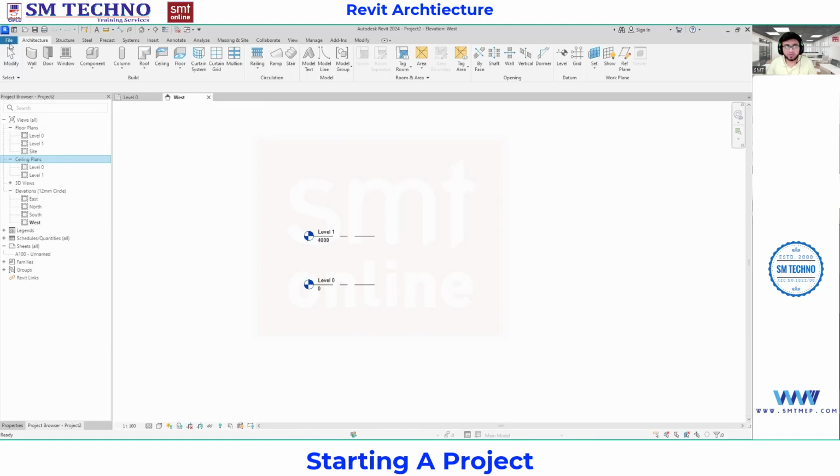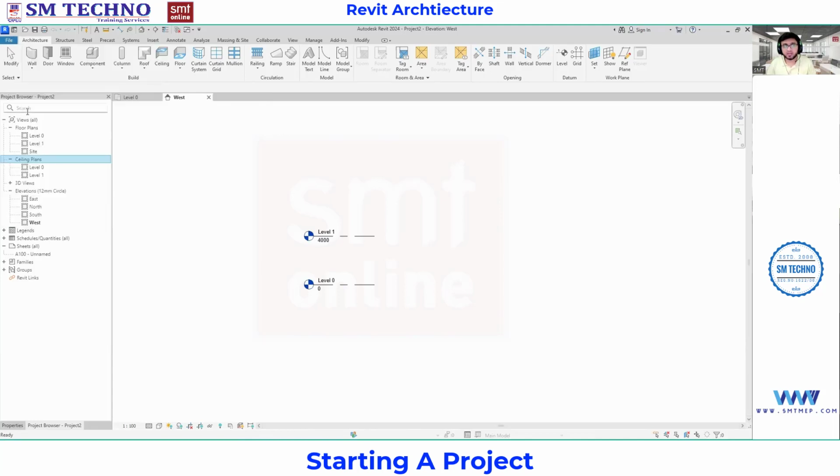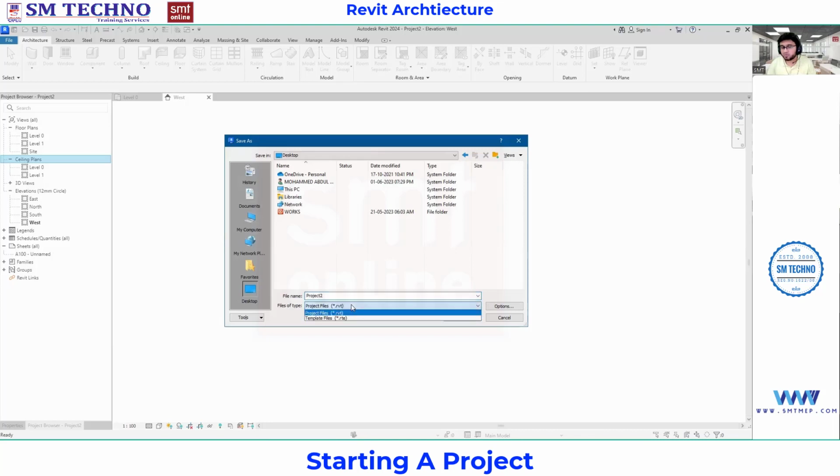So if you want to save your file, nothing but the project file, what we are going to do is go to the application menu and click Save. When you click Save, first provide the path where you want to save. Like, I want to save on desktop with Project 2 as the file name. And in which extension can you see .rvt, because we are going to work with the project file.